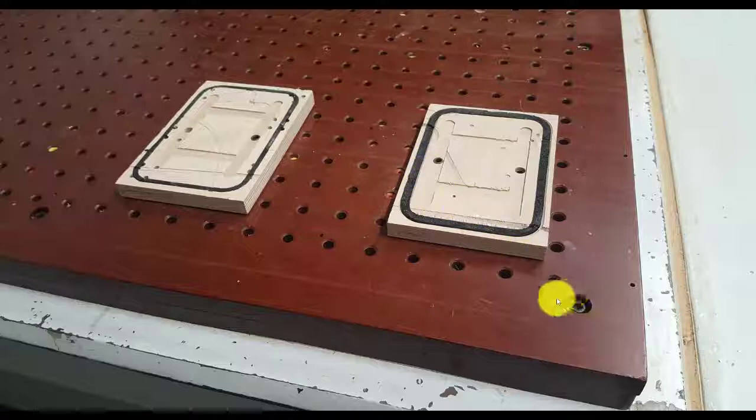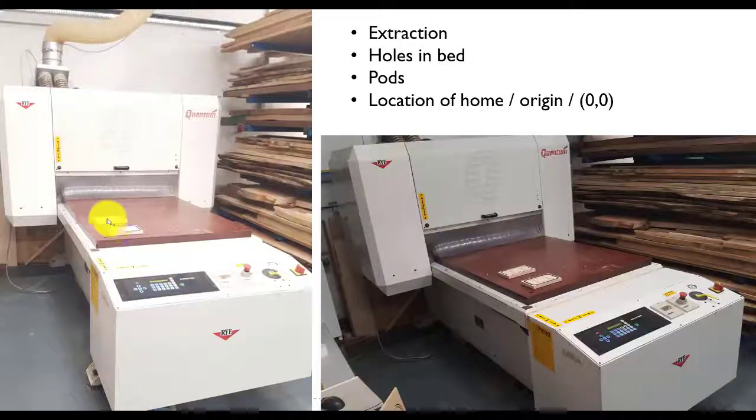It's important to note that this corner where my mouse is now is not the origin of the machine. If I backtrack for a second, the origin of this machine is way back in there under the machine head. That is 0, 0 in this machine. That makes it a little complicated to actually set up and position the piece. You have to lift this hood and reach in under this dust guard and actually position the pieces at 0, 0. So in practical terms here, we always use this machine off this corner.